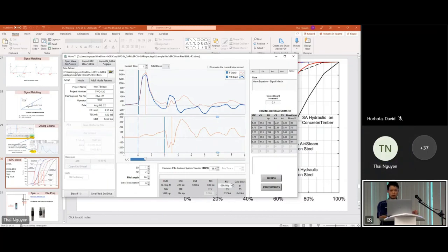Now, remember that for the production pile, the pile length may be different. So you have to change the pile length here. It's really simple, whatever you earlier recommended. Let's say you recommended a longer pile, 100 feet for example. So you change it to 100 here. And if you want to be even more conservative,